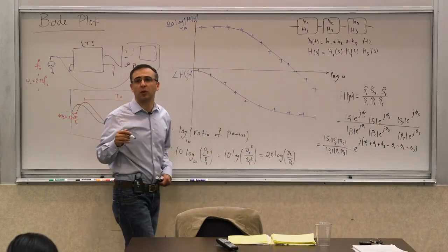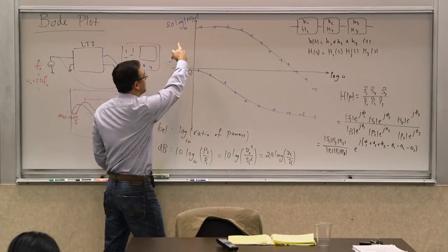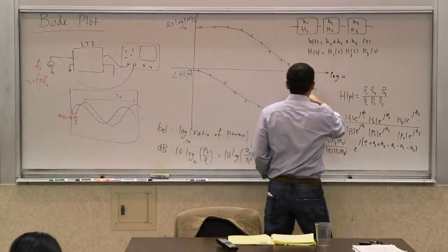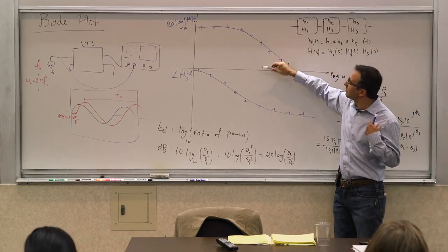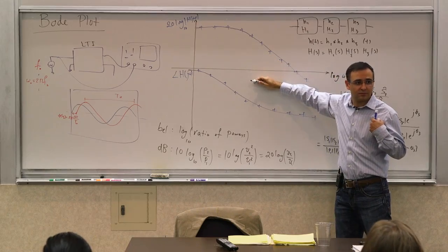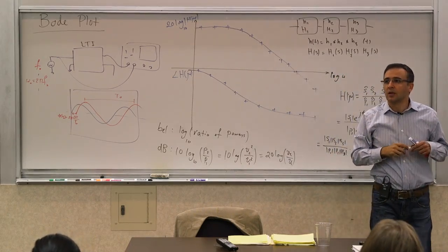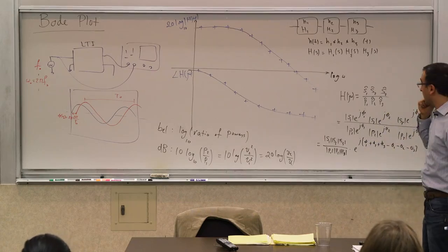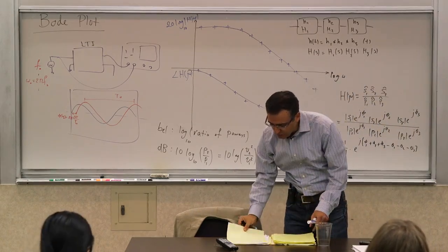But to make a magnitude part also additive as opposed to multiplicative, then you take the log of the magnitude part. Then that makes both of them additive. So if you have a cascade of 3 systems, and if you know their Bode plots, you can basically just add the Bode plots, the magnitude part and the phase plot. Magnitude with the magnitude, phase and phase, obviously. And then you get the aggregate Bode plot. So that's an interesting aspect of it, and it's useful.